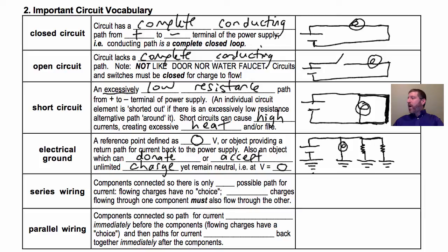And in fact, all the loads in your car, like your headlights, are connected to the chassis of the car, the frame of the car. So these are all connected to one giant piece of metal, or one ground it's called. And that allows all the charge that goes through here to flow back to this battery, as it must for a complete circuit. So this is very convenient when you have a big circuit diagram, because then you don't have to draw a line that goes all the way back to there. You can just ground it no matter where it is on your circuit diagram. Showing a ground and having your negative terminal grounded means those two are electrically connected.